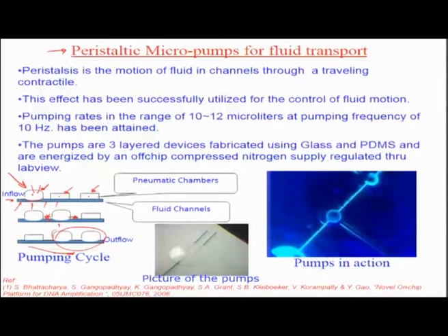So, this is exactly how you can operate a discretized fluidic system, and obviously it demands a lot of actuation, because all these are air actuated or pneumatically actuated, where cylinders are being inflated, deflated, typically in a material which is flexible, and creating a pinched effect on another set of flexible channels over which these cylinders are mounted.